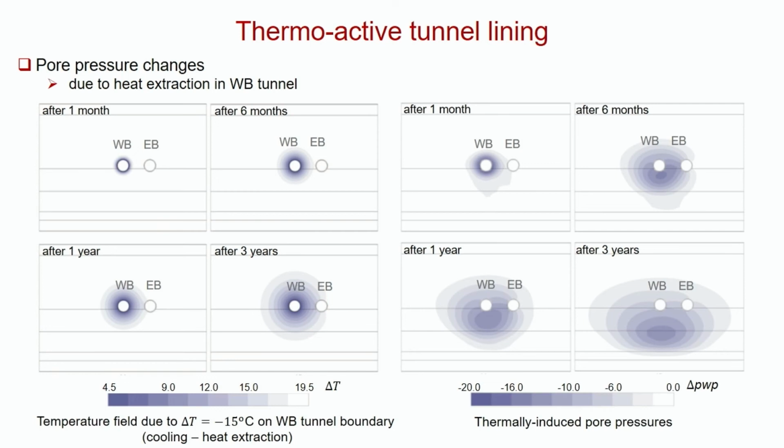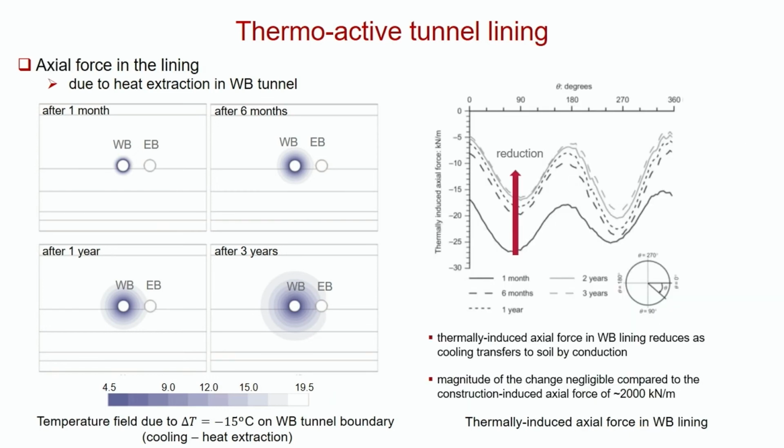It's not very permeable, it's London clay, so the water can't dissipate, so we get these negative pore pressures. And they're not symmetrical around the tunnel, and this is because it's a complex boundary value problem, and gravity is affecting the water flow and all the rest of it. And we do get changes in stresses in the lining. It's here, this is the thrust in the lining.